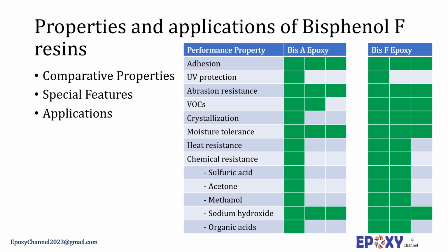Generally, unmodified Bisphenol-F based epoxy resins have very good chemical resistance and good mechanical properties and are lower in viscosity compared to Bisphenol A based resins. When properly formulated with Bisphenol A, they help reduce crystallization tendency and find application in adhesives, laminates, coatings, and civil engineering.